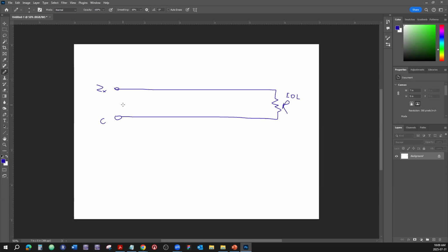So in order for the zone to be at rest, it needs to see that resistor. And then, of course, somewhere in series, we're going to have some sort of a device that is normally closed. What this gives us is extra security protection, because if this were just a closed loop, somebody could find the wire and short it. So if this thing opens, then the zone is not going to react.